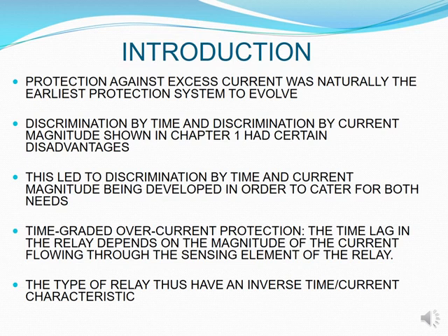We call this situation a time-graded overcurrent protection system. Really what happens is that you've got a time lag. In other words, there must be a delay in the manner that the relays are going to open for the same fault that they see in the system. What you want in your timing is that the relay closest to your fault must hit it first, and then the relay that is furthest away must first delay before it can take out that same fault.